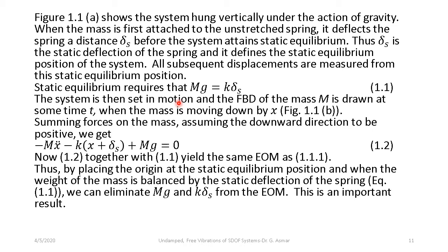So the system is set in motion, and the free body diagram of the mass is drawn at some time t, when the mass is moving down by x, as shown in figure 1.1b. So this is when I freeze the system. I freeze it at the time when the mass is at some x below the datum, below the static equilibrium position. We have the forces acting on the mass, which are the weight mg, the reaction from the spring k times delta S plus x,